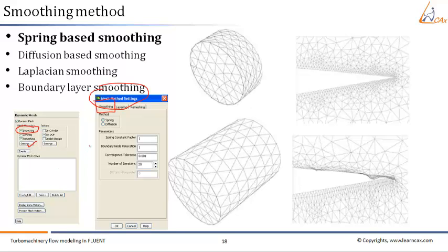And the mesh is smoothed using the spring based smoother but limited to 20 iterations. Degenerate cells are created with the default value of 1 for the spring constant factor. You can get the original mesh distribution recovered if the spring constant factor is reset to 0.